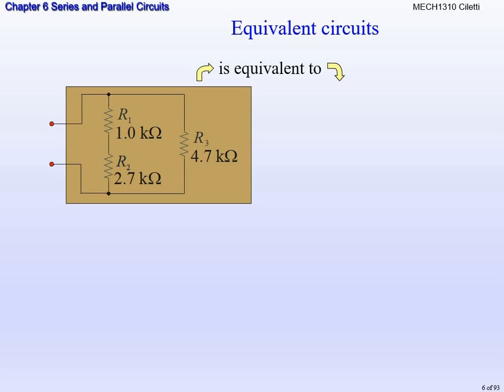So what's going on here? I want you to see if you can identify real quick. R1 and R2, what's the relationship between R1 and R2? They're in series. So we would do that series connection first, right? That series connection is in parallel with R3. Does everybody see that? If R1 and R2, we'd have to do that connection first and find that total resistance.